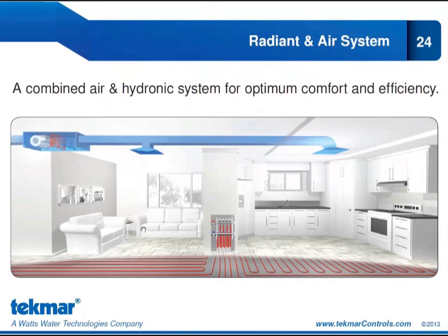So the radiant heating typically can provide all the heating needs, and the radiant cooling can only address typically part of the sensible cooling load. We have to think of the overall cooling load, and in particular that latent cooling load, that humidity. So a forced air system is always strongly recommended.